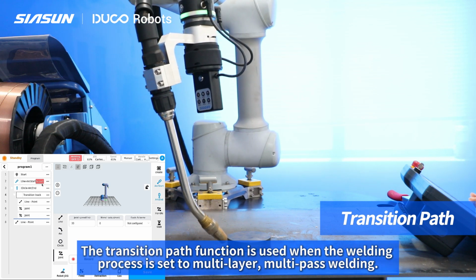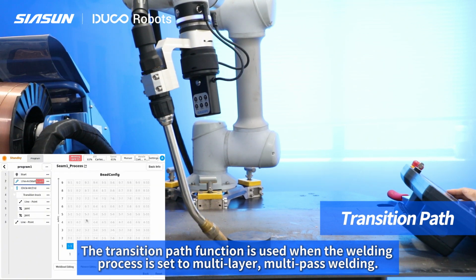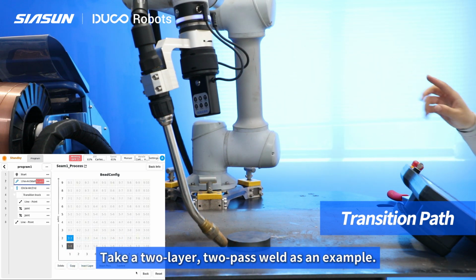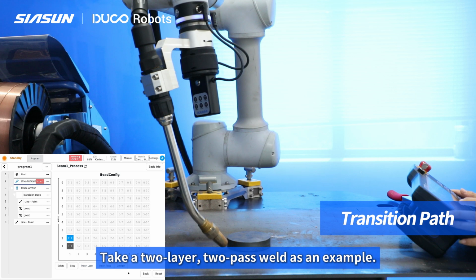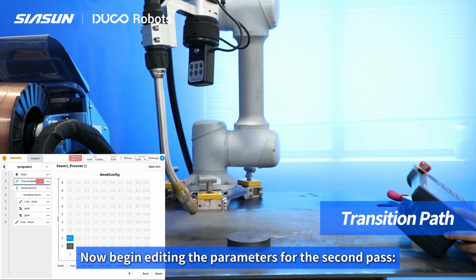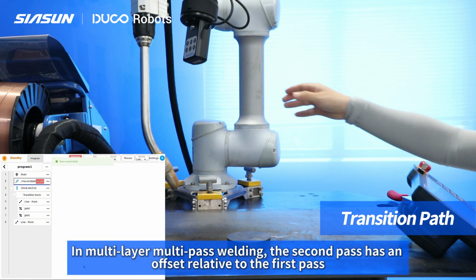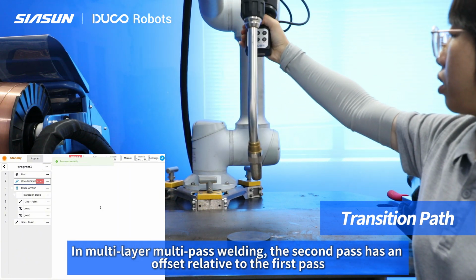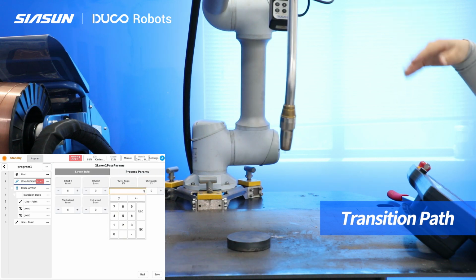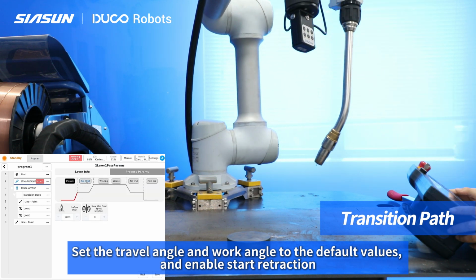The transition path function is used when the welding process is set to multi-layer, multi-pass welding. Take a 2-layer, 2-pass weld as an example. Now begin editing the parameters for the second pass. Click Process Edit. In multi-layer multi-pass welding, the second pass has an offset relative to the first pass. Enter a Z offset of 5 mm. Set the travel angle and work angle to the default values, and enable Start Retraction.